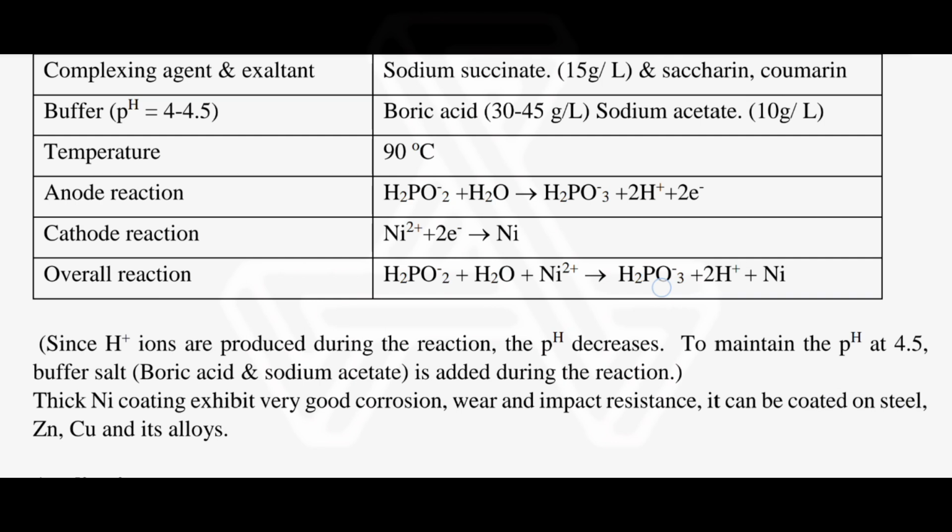Temperature, 90 degrees Celsius. Anode reaction: H2PO2- + H2O gives H2PO3- + 2H+ + 2e-. Cathode reaction: Ni2+ + 2e- gives Ni.